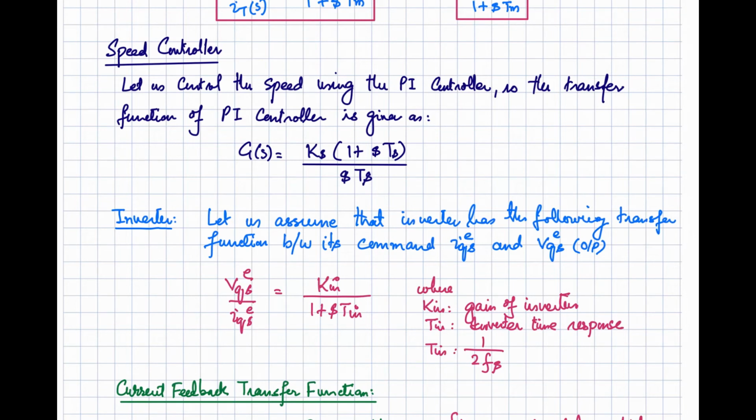It varies from application to application. If you have a space vector pulse width modulation based inverter, in that you require the voltages as the reference, so you will have to translate this IQS in terms of the voltages. Those will be applied as a control command to your inverter, and then it will realize that control voltage at the machine terminals. So it varies from situation to situation, but over here we are assuming that the current command is the input, and the voltage will be realized across the machine terminals by the inverter, and this is the transfer function of the inverter.